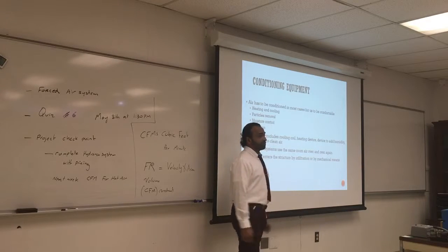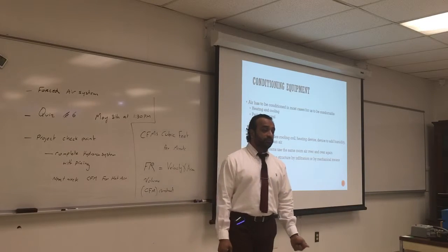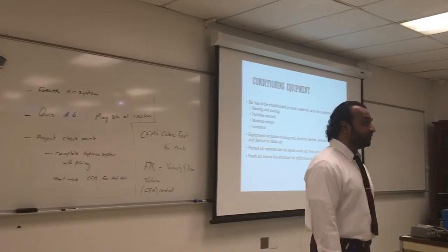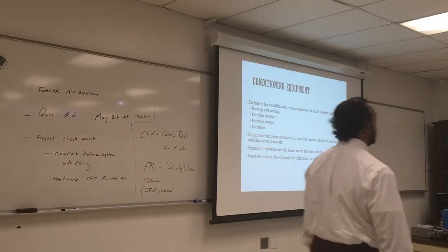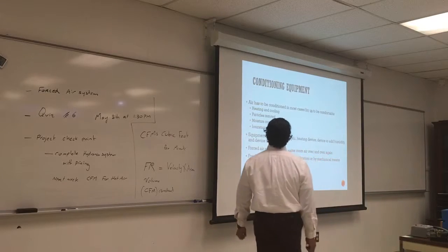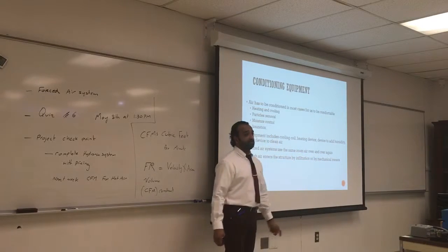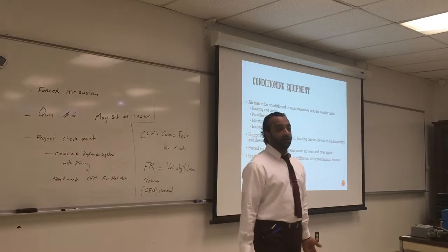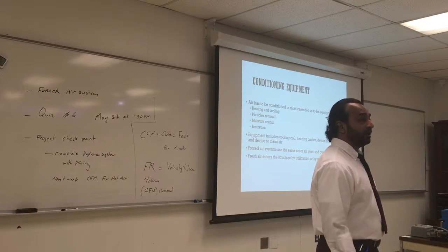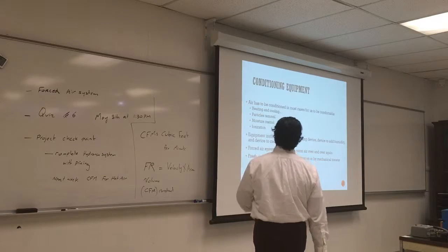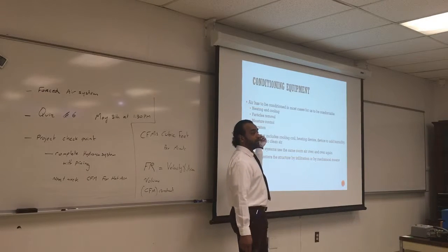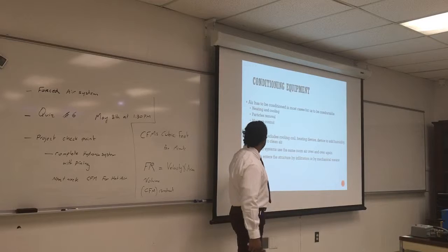We can also do moisture control. Most of the time when the air is hot, it gets very, very dry. So maybe we can add the proper amount of moisture into the system. One last thing is we can do ionization. This is a new feature, a new fad, to ionize the air to make it more comfortable, and also make it attract more particles, sticking to the filter.